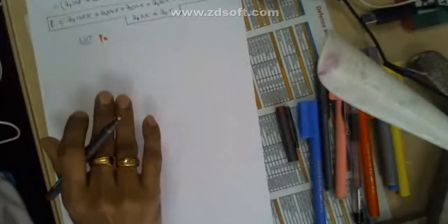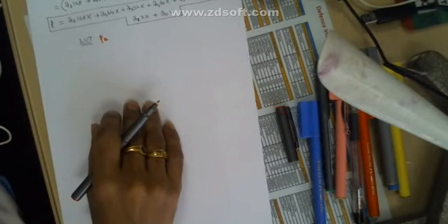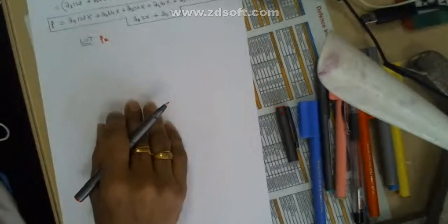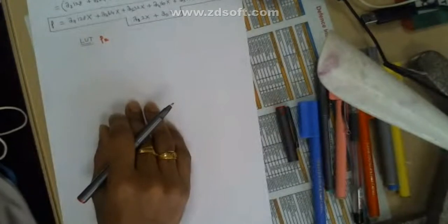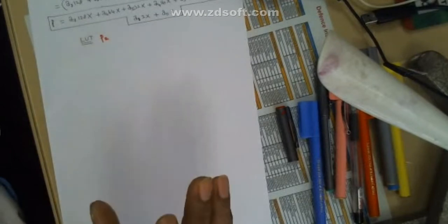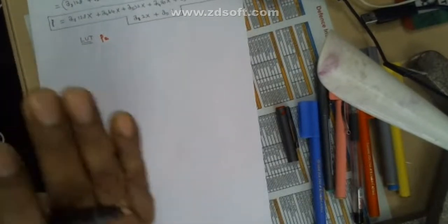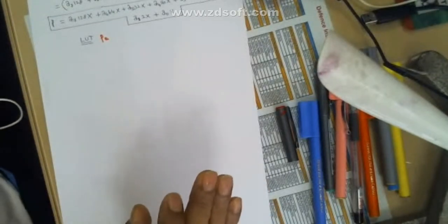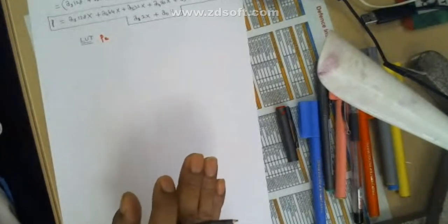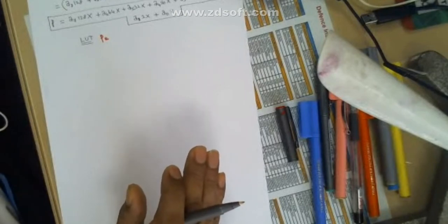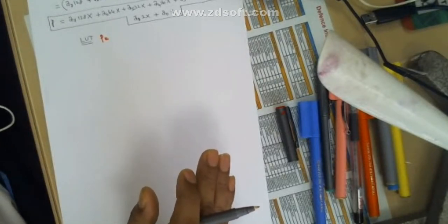In the last lecture, we saw the pipelined architecture design. What is the advantage of the pipelined or parallel pipelined architecture? How do we improve the throughput of the circuit? By just inserting the intermediate registers. That means we need to divide our entire application, or your big Boolean equation, into small modules so that we can improve the throughput. That means we are reducing the latency, so our clock speed will be increased due to the reduced latency. That will obviously increase our computation speed or throughput.